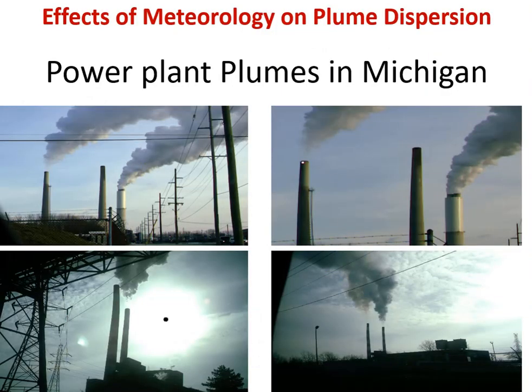As I told you, when the environment is stable, then the flow of the air is smooth. Here it is showing the different types of the plume which are emitting from the Michigan power plant. For example, in a stable condition, the plume moves smoothly in one direction, but if it is very unstable like this one, it will go up quickly, and with the mixing, there is more mixing. So that is the plume formation and its movement. It can also explain the atmospheric stability.